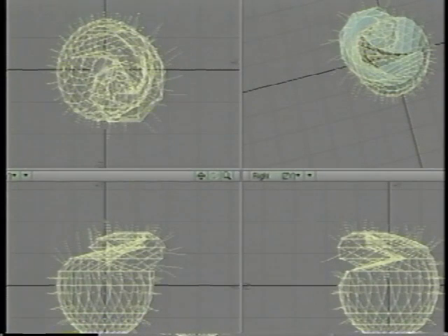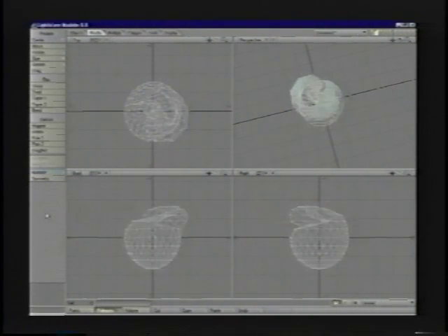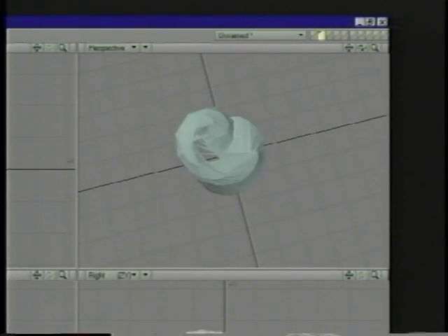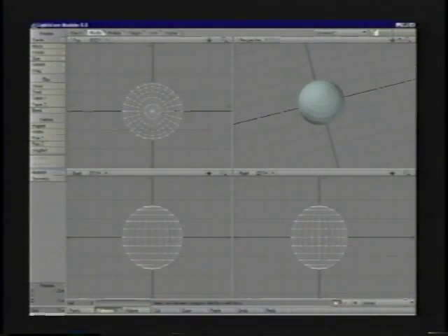Okay. So how can we fix that? Ye old triple. So Shift-T, triple. No non-planars anymore. All right, but anyway, the point being that you can really mess up your geometry with those tools, and now you know how to fix those.